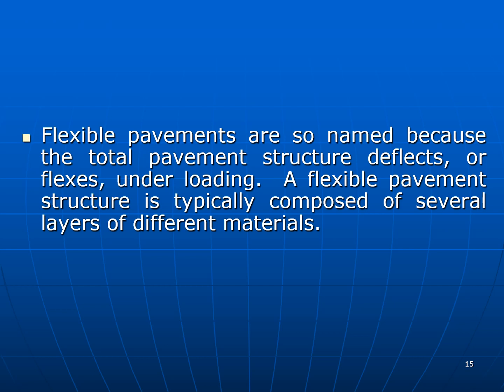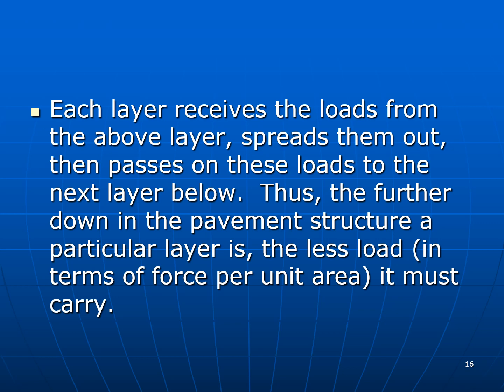Flexible pavements are so named because the total pavement structure deflects or flexes under loading. A flexible pavement structure is typically composed of several layers of different materials, as you have seen on the previous slide. Each layer receives the loads from the above layer, spreads them out, then passes these loads on to the next layer below.